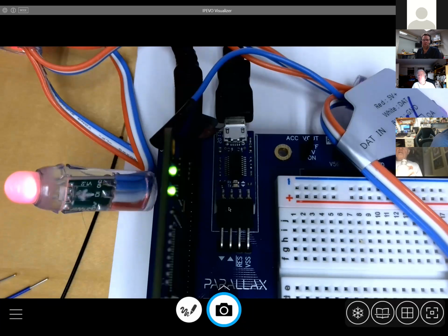Hey, Carol, I had this issue too. Make sure that you remove all of the old drivers. Go to the control panel, add remove programs, get all of the older versions of the drivers out, uninstall the prop tool, and then reinstall it, and it will install the latest ones. You probably just have too many versions of it in there and it's confused. Okay, I have it on a separate computer where I only have the version 2.4 on it. The things I'm doing with version 1.3, I'm actually doing on a different computer. Oh, okay. And then I've also gone through and tried hand picking the driver from the Parallax drivers that are already available. And I'm not sure which one to hand pick to make it work right, the ones I've tried so far.